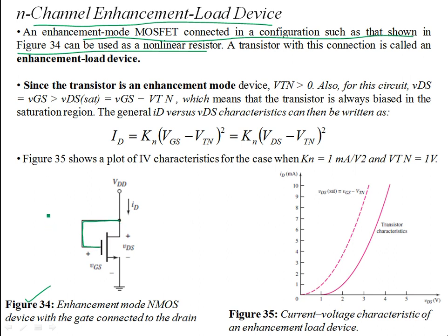So VG and VD are equal over here. That means VG is equal to VD, which in turn is equal to VDD. So VDD is the final controlling supply voltage that defines the potential at drain and at the gate, because your source in both VDS and VGS is set to 0. It's a common source circuit.